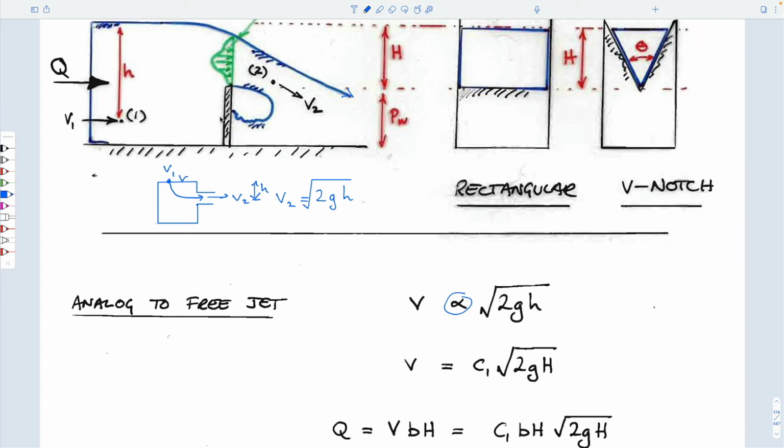All it measures, with a pressure transducer or with a float, is the height of the water that's in the stream, because there's direct connection between that little vertical corrugated pipe and the stream, so it mimics exactly the rise and fall of the stream. It measures that pressure as a depth, and so it knows this height relative to the magnitude of this.